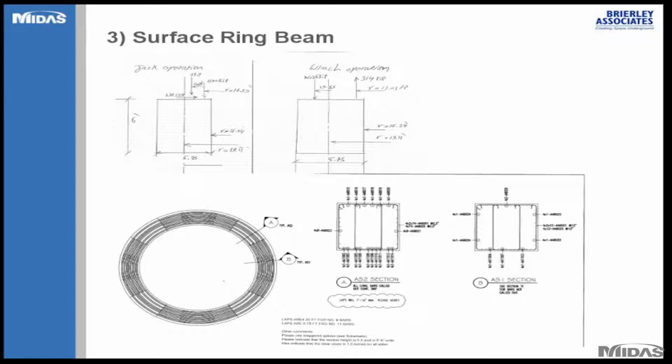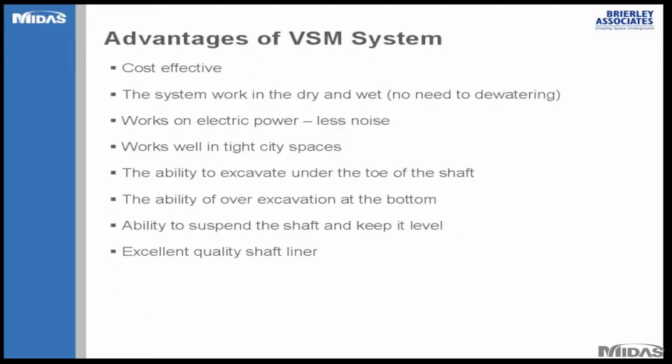This significantly reduced the moment, and in fact we didn't need any reinforcement at the bottom for this trim slab. It was about a 10 foot thick trim slab, and the construction is done, it's holding still and working fine. And we're getting ready for the breakthrough next.